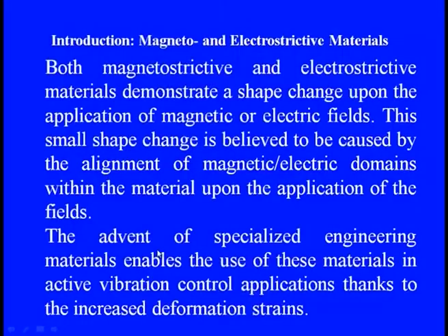In this lecture we are going to discuss a similar feature, with magnetostrictive or electrostrictive materials. What does it mean? Both the magnetostrictive and electrostrictive materials demonstrate a shape change upon the application of these fields, the magnetic or electric fields, and the shape change is very sensitive to the intensity of the magnetic or electric field.